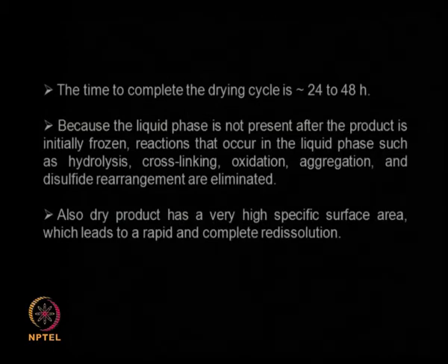So reactions like hydrolysis, cross-linking reactions, oxidation reactions, aggregation of the solid material, and disulfide rearrangement are all prevented. Also, when you dry the product completely, it has a much higher surface area per volume. So if you want to redissolve it into some solvent, it is very rapid and complete. That is the advantage of a lyophilized product.